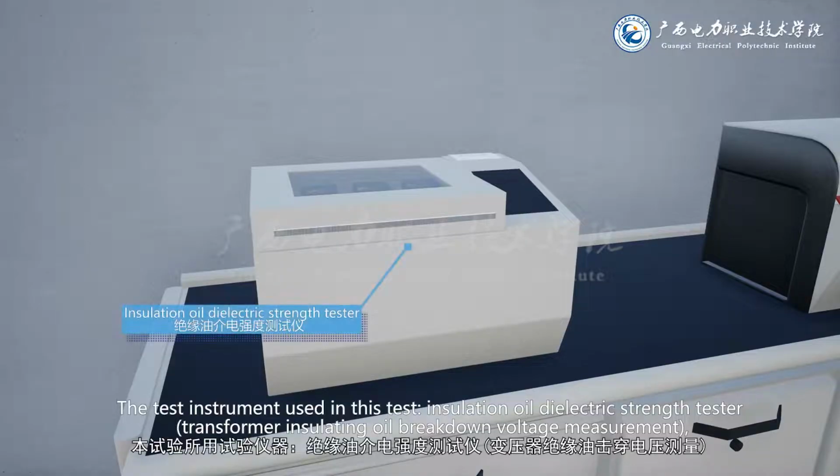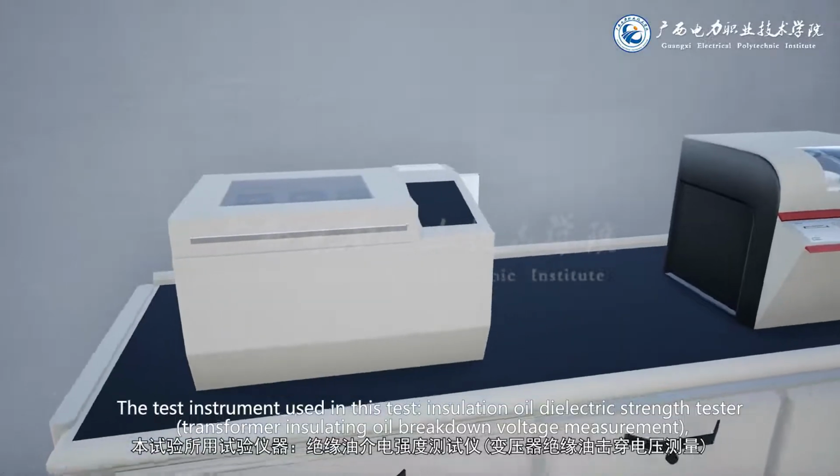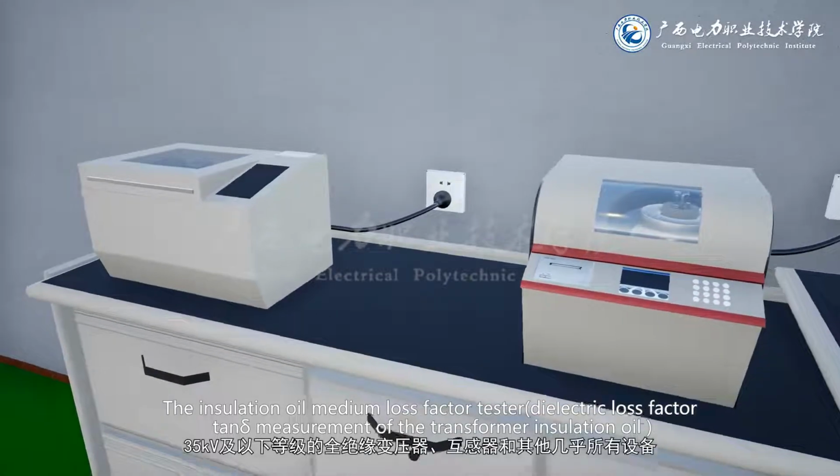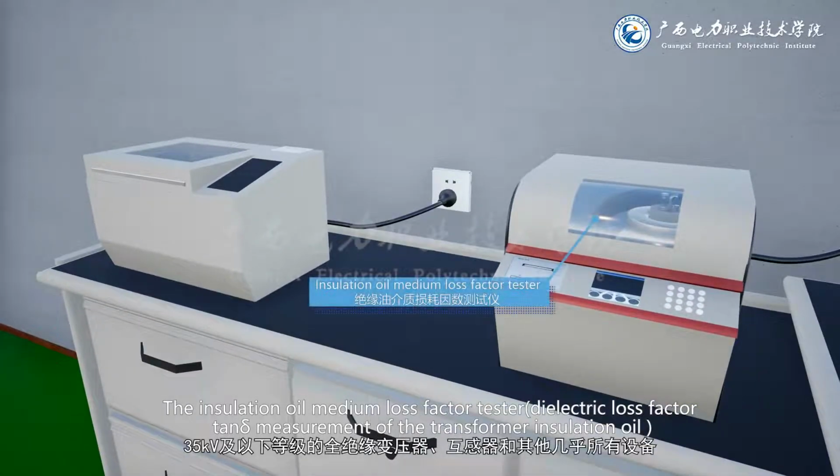The test instruments used in this test: insulation oil dielectric strength tester, for transformer insulating oil breakdown voltage measurement, and the insulation oil dielectric loss factor tester, for dielectric loss factor measurement of the transformer insulation oil.